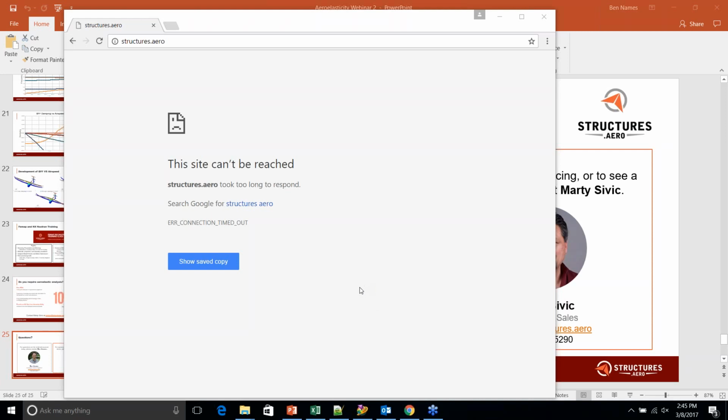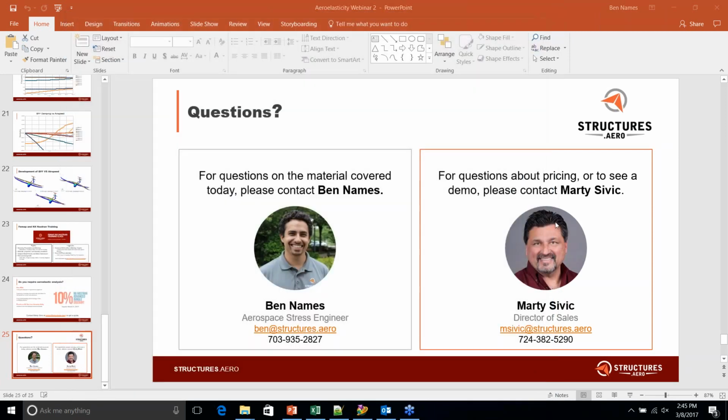Does the number of velocity points in a flutter analysis help the mode tracker? Yeah, absolutely. Again, one point I should actually mention. In theory, that would work. Nastran, at least for the basic Flutter analysis, does not actually support mode tracking.